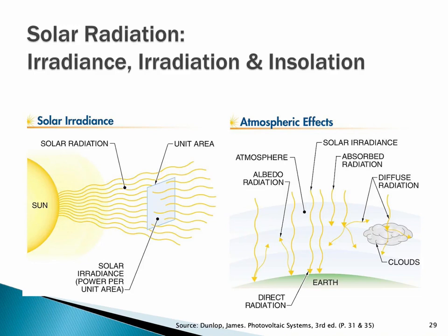We have a white roof surface, and this fall I was absolutely flabbergasted when we put the irradiance meter on the array at the same angle as the array, and the array was seeing 1,200 and some watts per meter squared. We had this additional 200 and some watts just from the reflective surface of the white roof. So we can enhance the performance of a system by landscaping or roofscaping.